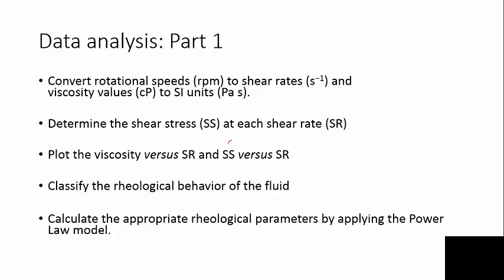Remember, I showed you shear stress versus shear rate, which is the definition of viscosity. The shape of that curve is what you use to classify the rheologic behavior. And then if it's a curve, you need the power law. If it's a straight line, you can just use a linear regression and the Newtonian relationship.